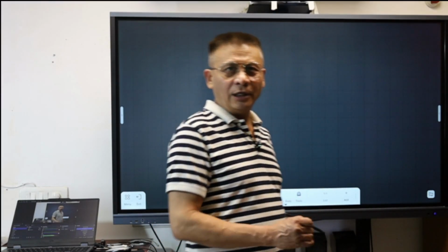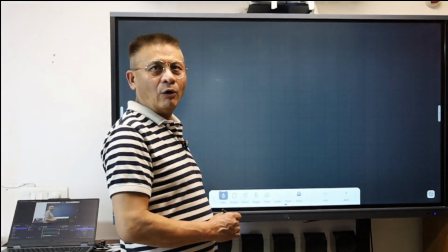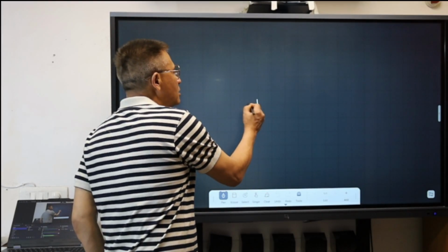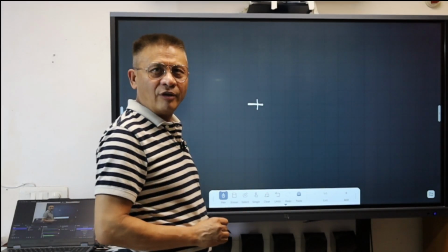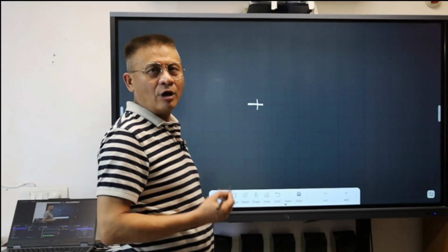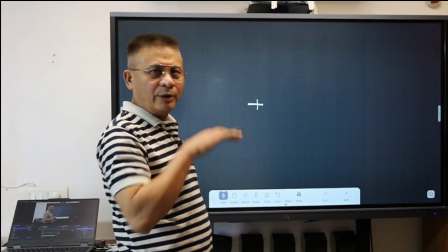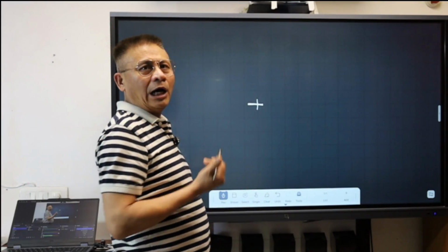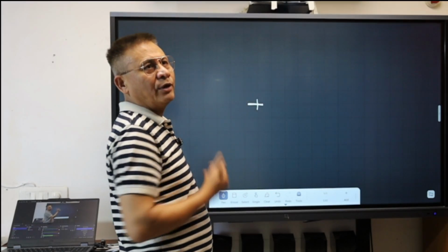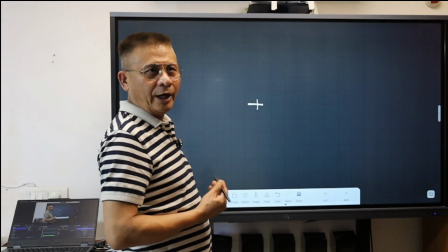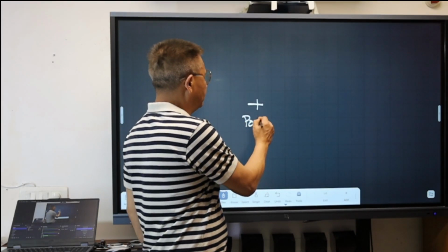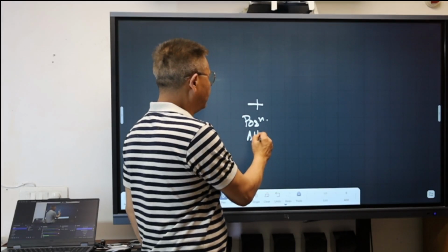Now let's move on further from that. The accelerometer measures the acceleration in the direction in which it is aligned. So let us assume that this is the starting point. The coordinates and the altitude of that point are known to you already. Whenever you park an aircraft at the parking bay, the coordinates along with the elevation are written right in front of the cockpit where the aircraft is parked. So you know the position and the altitude of the aircraft.